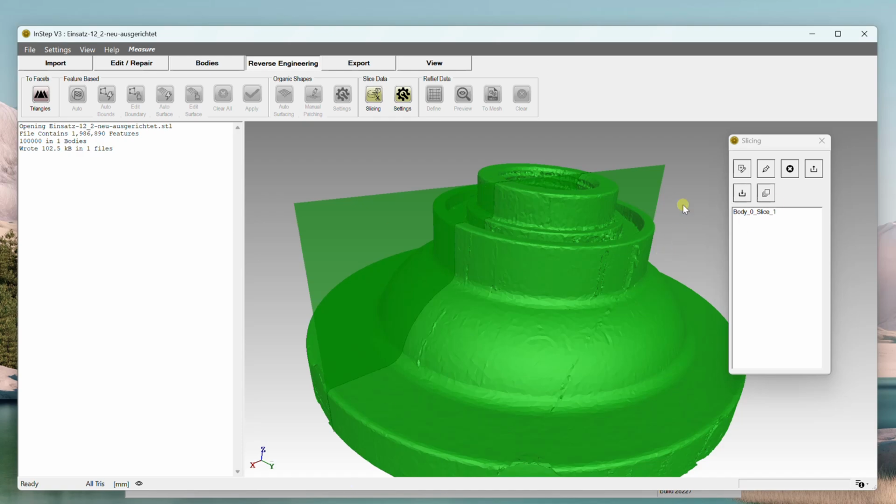The slice file itself does not actually contain these. So, and this may be something I should mention as a recommendation here, if you're working with a body like this, you may want to defeature it down to a level that's easy to work with, just like we did now.